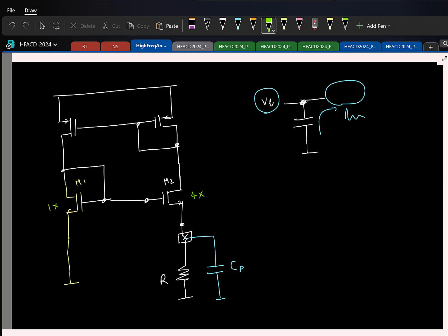Now sometimes people also tend to put an explicit capacitor here because this is also supposed to be a DC potential, right? So let us say you put that, and total cap I call it CP. Let us say you put a large cap here. Do you foresee any issues here, or things will be fine? Okay, first, I don't know if you recognize it. Let's not even consider the capacitor now, let's look at the DC picture. So what kind of feedback do you think we have here?